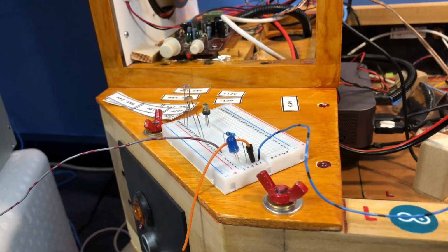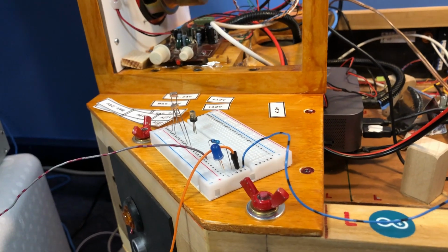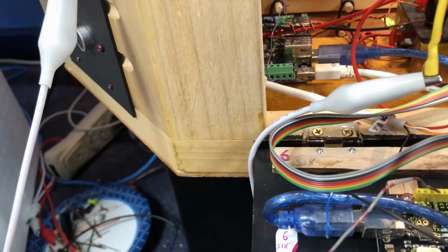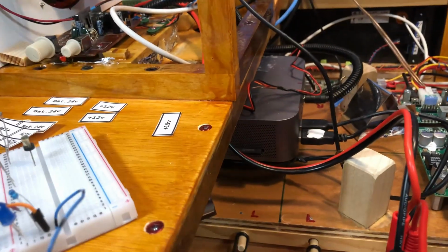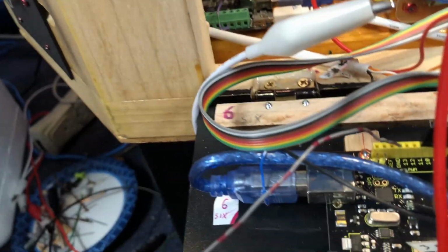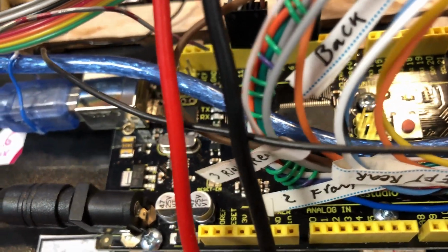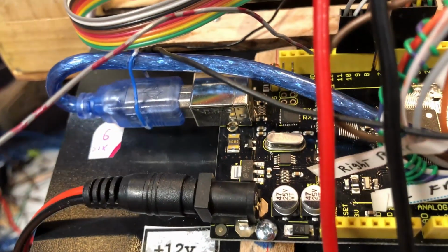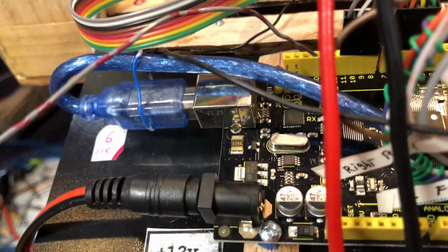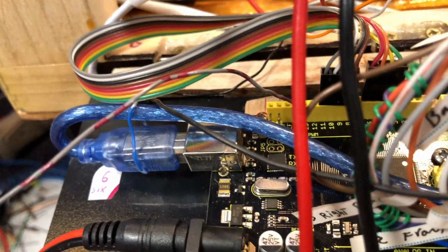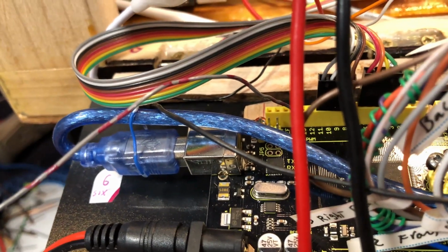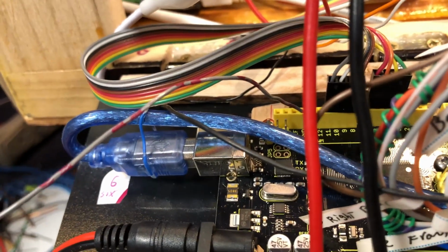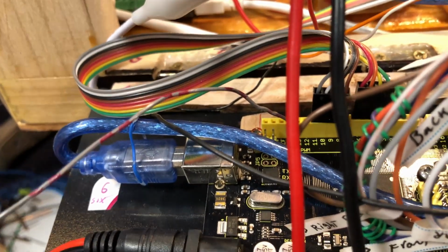I'm going to apply power to the 12 volt DC-DC converter, which will then supply power to the 24 volt or the 19 volt DC-DC converter. That'll give power to the PC. It'll also give the 12 volts power to this AT Mega. The Mega's program is set to pull a pin. Well, it's going to leave a pin high for like 5 seconds. It's going to pull it low for 5 seconds, and then it's going to pull it up high again for the rest of its career.